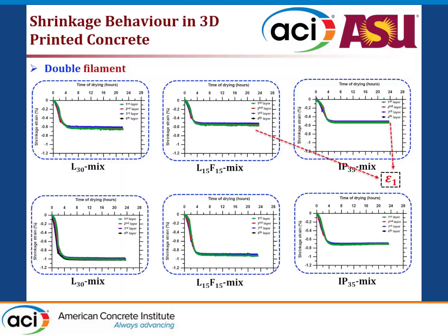But when you actually remove that restraint effect from the double filament, your value from the double filament and the single filament are similar. Now, I am calling this a free shrinkage. If I did not point it out in the previous slide, I assumed the restraint against thickness for the single filament to be 0. So when I say E free, the free shrinkage is this, it's based on a single filament. I am calling the single filament's shrinkage after removing the vertical restraint E free.